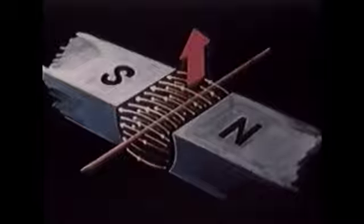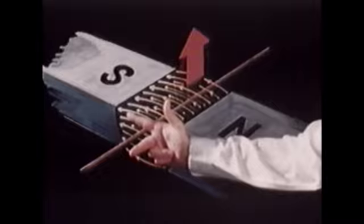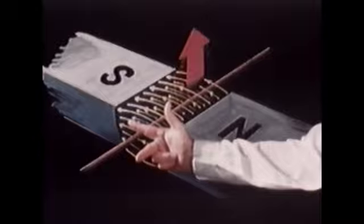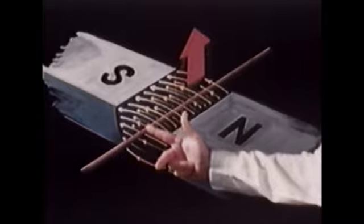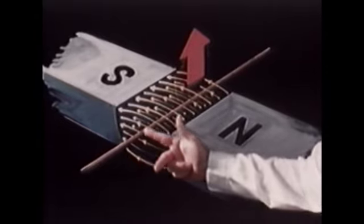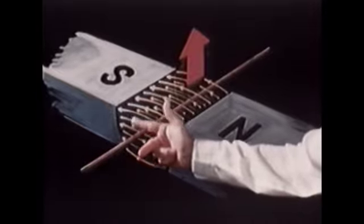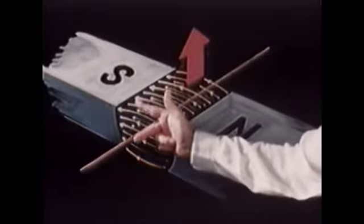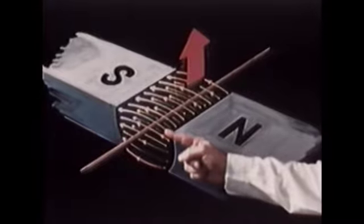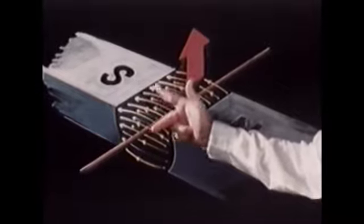To determine current direction, we use Fleming's right-hand rule for generators. Extend the thumb, forefinger, and center finger of your right hand so they are at right angles to one another. Point the forefinger in the direction of the magnetic field, from the north to the south pole, and the thumb in the direction of the conductor's motion. Your center finger then points in the direction of the induced current. You might remember that F is for forefinger and field, T is for thumb and thrust, and C is for center finger and current.